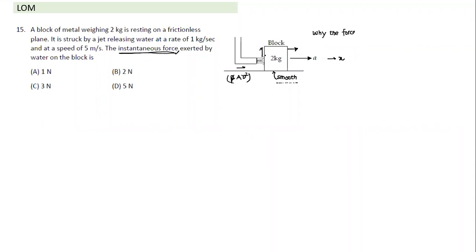Change. Mass striking. See, what is the mass which is passing through the pipe? The mass which is flowing through is written as rho AV and the value is given. It is 1 kg per second. But after it starts moving, will the mass which is striking the surface remain 1 kg per second or will it change?